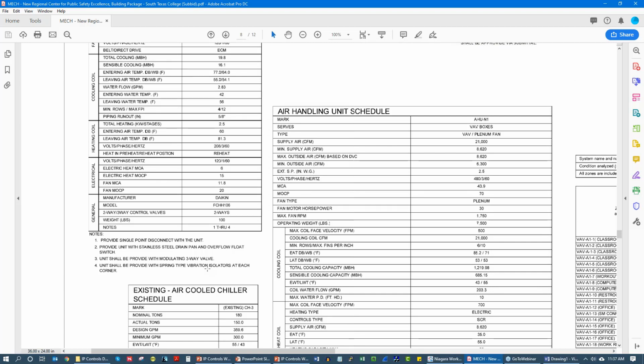But here's the deal. That violates the whole point of a star pattern, because the benefit of the star pattern is not, hey, the controller's closer, so I'm going to pay a little bit less in wiring and have one less port that I need to request from IT. The real benefit of a star pattern is that I've decoupled myself from that ring or that bus. So if that ring or bus fails, my air handler is still running. My chiller is still broadcasting information.